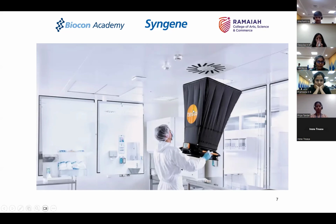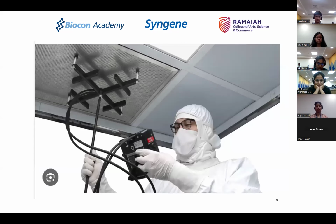In earlier days, they used to use anemometers. There are other types, like we have one more equipment like this. This is a flow meter. Can you see this one, a stud-like piece here? That is to ensure that we are taking the velocities at the right level. This measuring tool should not be too near to the grill or too far from the grill.